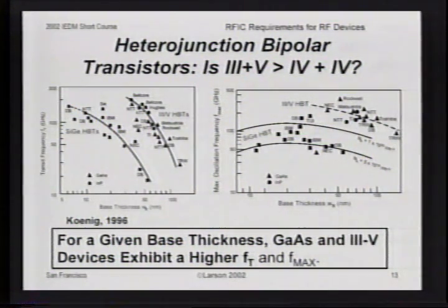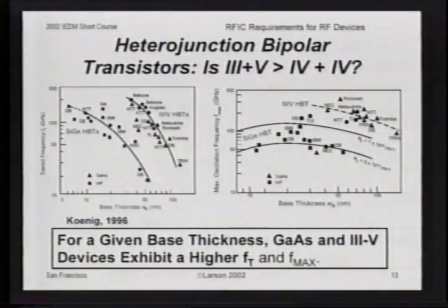Now, as I said before, and as we'll see as we get into the presentation, this sort of intrinsic advantage doesn't buy you a whole lot, because actually, as Professor Abidi said earlier, the existing technologies are good enough for almost any application. The one exception is with power amplifiers, where we often operate them right to the very limits of their breakdown voltage capability. Every little bit of extra Ft that you get at that limit has a big impact on performance. Since power amplifiers loom so large in power budgets of modern transceivers, this becomes a major issue.